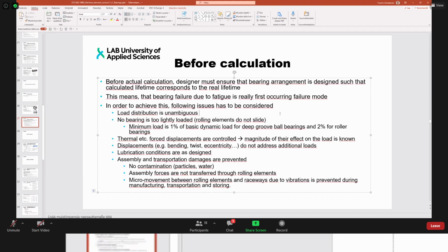And also something we already spoke a bit about is the assembly and transportation. Those are usually the places where the problems occur. The engineers design the bearing system and there's proper lubrication, but in the assembly, either the tools are not appropriate, or there's some possibility for a careless assembler to assemble them in a way that introduces force through the rolling elements, or other means.